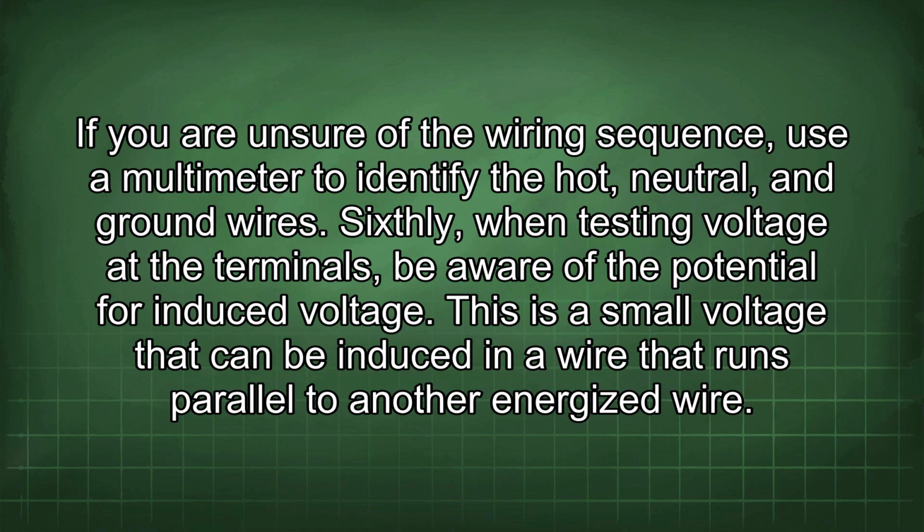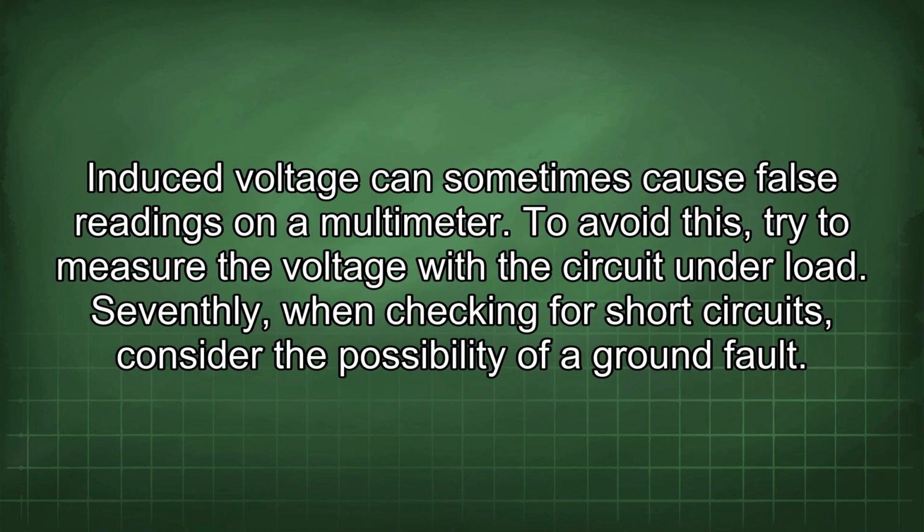Sixthly, when testing voltage at the terminals, be aware of the potential for induced voltage. This is a small voltage that can be induced in a wire that runs parallel to another energized wire. Induced voltage can sometimes cause false readings on a multimeter. To avoid this, try to measure the voltage with the circuit under load.